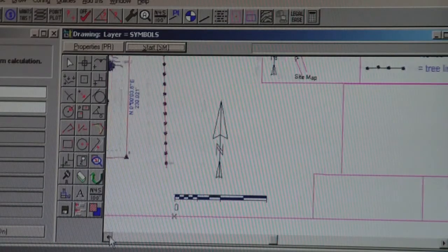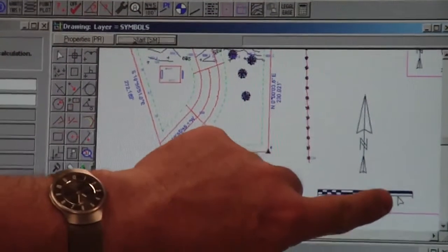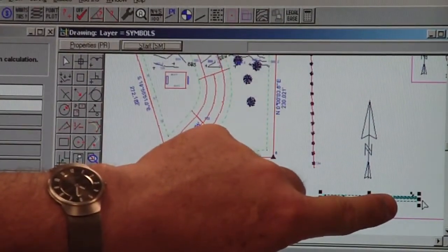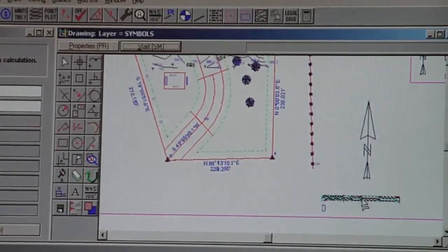Now, how do we find out what the scale is? Well, you got to make a test print. And you're going to measure this. And let's say with a ruler, 2 inches on your 11 by 17 sheet of paper comes to right about there. So you're going to hold your pencil or your finger on the screen. I'm going to click on this. Now this is really scientific, and I'm going to squeeze this down to about where I've got a 2 inch bar. And I'm going to move this over.